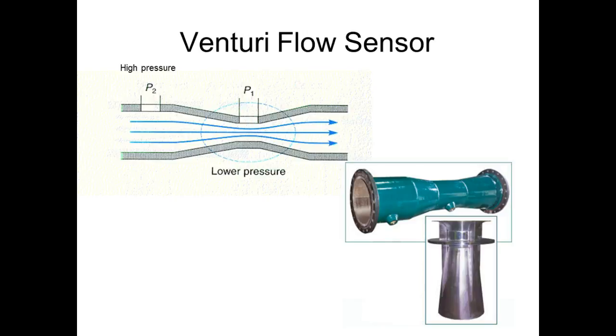Anybody's got a pressure washer. Most pressure washers have this thing. So you can come out there and you can put a tank on the outside, right? You understand? And even though that pressure is coming through there, why doesn't it come out there? Well, they send it to a Venturi, which creates low pressure, right? And what does it literally do? It literally takes your soap or whatever you're washing with and sucks it into the stream. So if you got a pressure washer, most pressure washers have a Venturi inside there, so you can add things, right? Like soap and stuff like that.